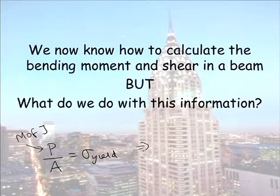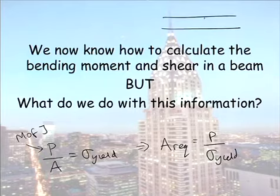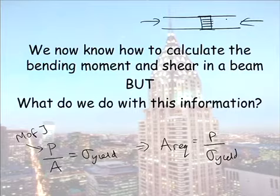So rearranging this formula, our required area will equal our force on our yield stress. And then you go in your tables and you find an area. When we look at our truss members, they had axial load in them, so our stress distribution was uniform.